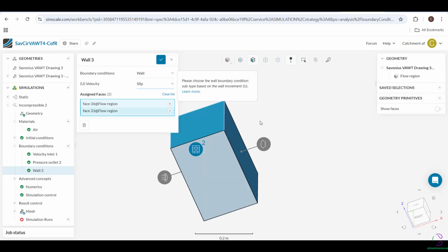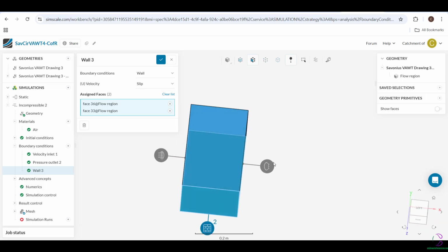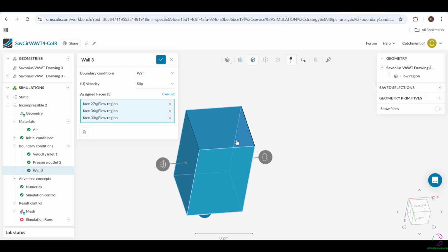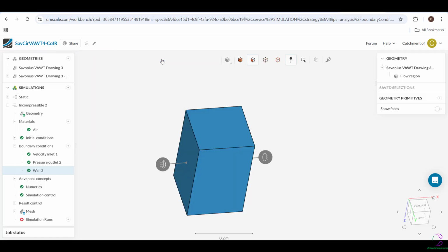You can always go back once you have a full understanding of SimScale. You can then go ahead and run a more elaborate analysis. I'm making all the other walls slip walls prior to the analysis. You can always adjust the mesh, but it will take time. Because this is a quick tutorial, we'll just take the default in the system, and then run this analysis. I adjusted the mesh earlier during some trials, and it took quite a long time.